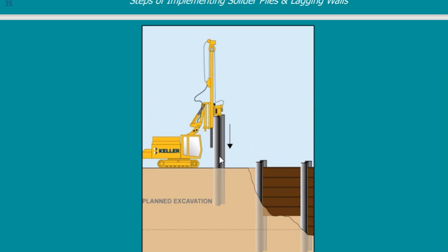So I put here an I section, an I section, and an I section. And I can pour concrete at the bottom so that the I section will be fixed in place, not just a loose I section. Suppose you are drilling 10 meters, maybe 3 meters from the bottom you can pour concrete. So now I have I sections all around my site.